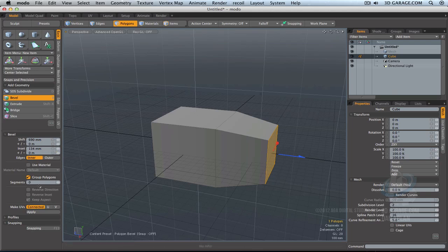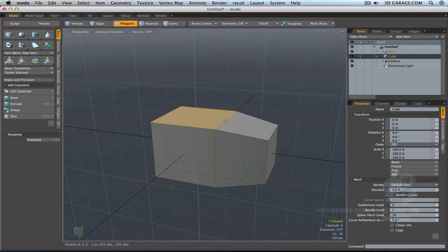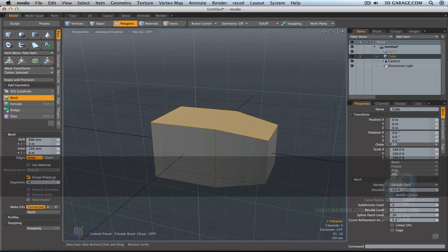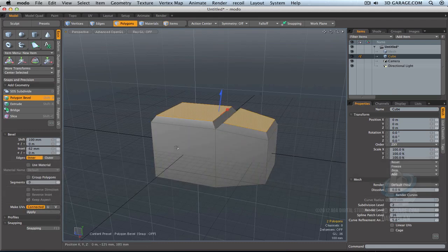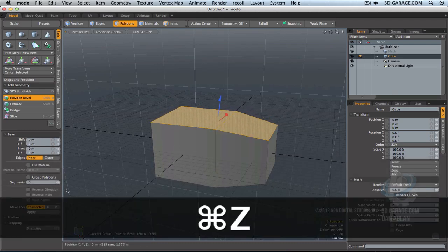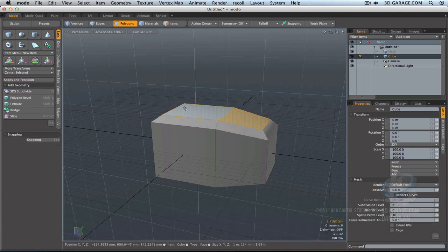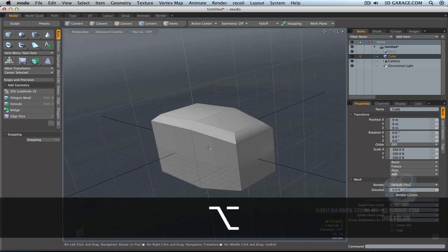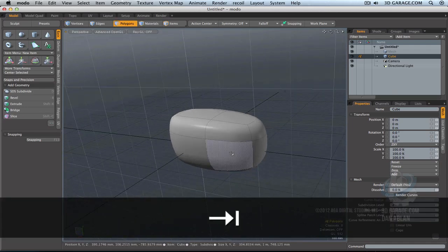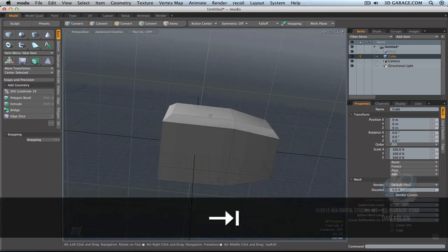But what's great about Modo's bevels is that it automatically will group polygons. So for instance, I've got 2 polygons up here now. Press the B key to get my bevel. If I turn this off and I click and drag, my bevel does that, kind of that Hershey bar effect. Group polygons, and now I'm beveling those together. Turn off the bevel, and then deselect. So easy to make shapes. And then tab key, I add subdivisions.